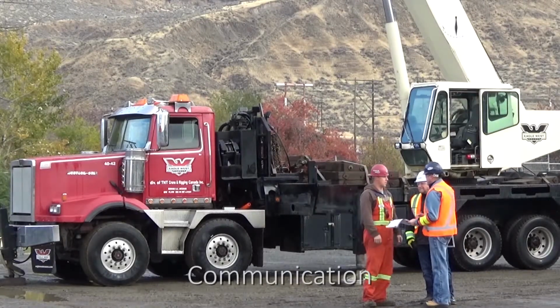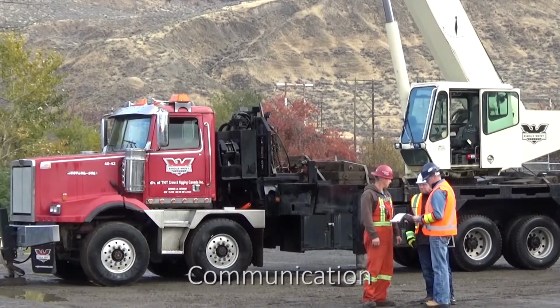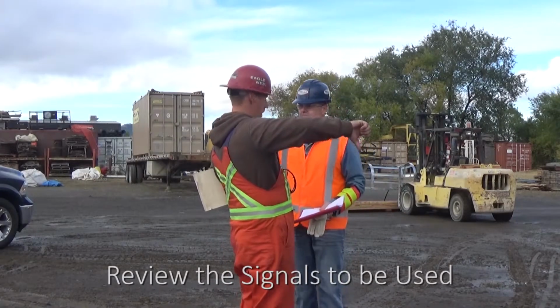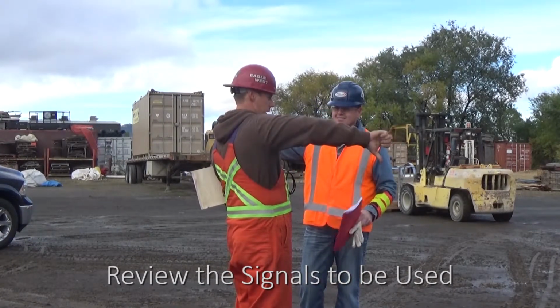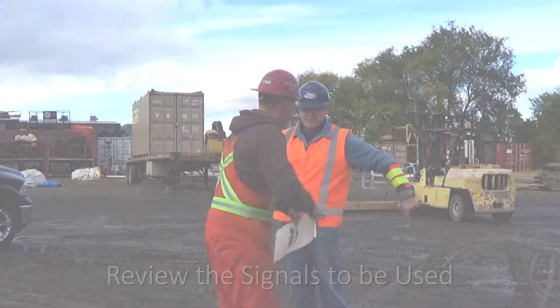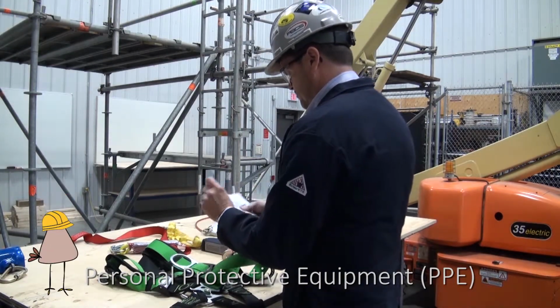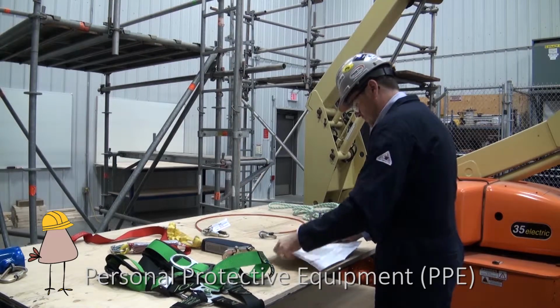Communication between team members must be planned, and your team performing the lift needs to be involved in the planning process prior to the execution of the work. If hand or radio signals will be used, the crane operator, signaller, and personnel involved in the lift will need to review the signals to be used. You'll need to determine what personal protective equipment will be needed and ensure that it is available and that anyone needing to use it is trained to inspect and wear it as required.